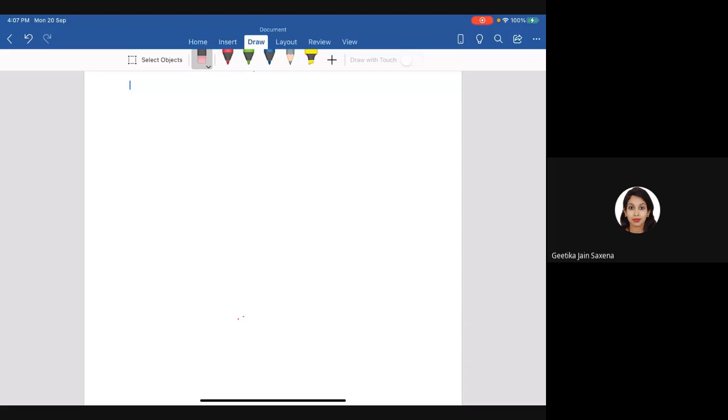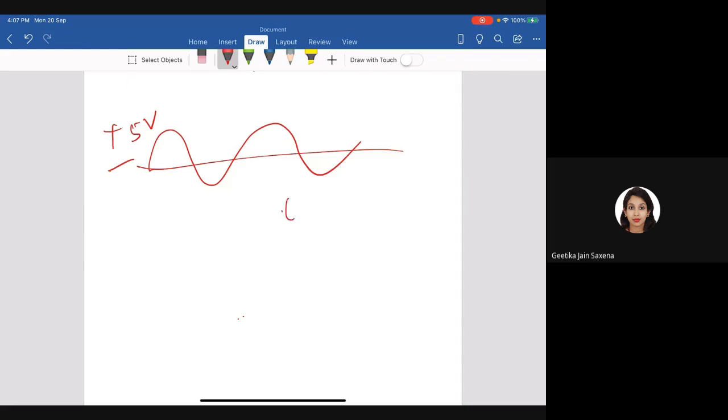So understanding this waveform, explaining it in a simple way, understanding what is in it, what is hidden in this wave, that is what we call signal processing. How? Whatever the signal you get, let's say I'll draw like this, right? Or maybe I'll give some time information, that this is varying plus minus 5 volt, and some information, let's say 1 second, and I ask what is this, then you can tell maybe it looks like a sinusoidal wave, and its peak is varying plus minus 5 volt, and this is present for t equal to 1 second. You will tell like this, okay, and this is what we call visual analysis.